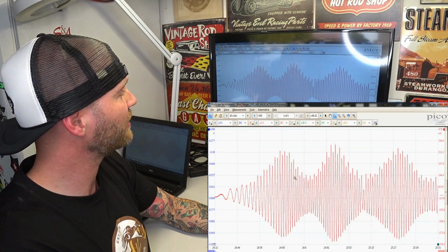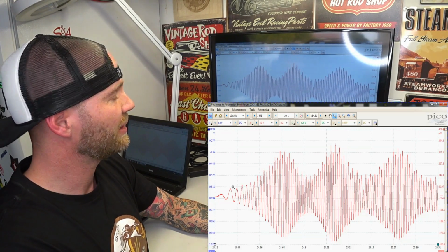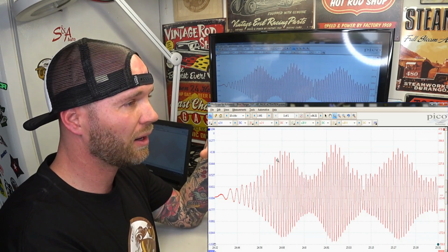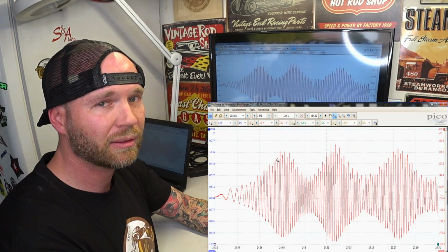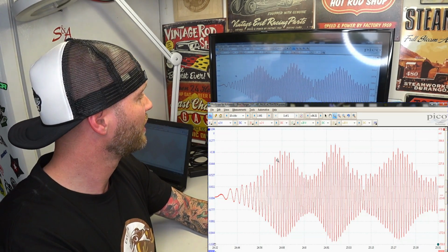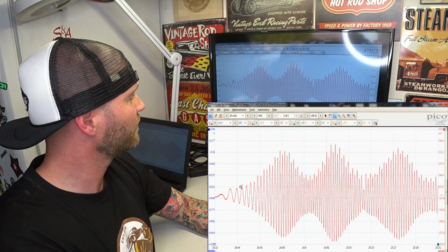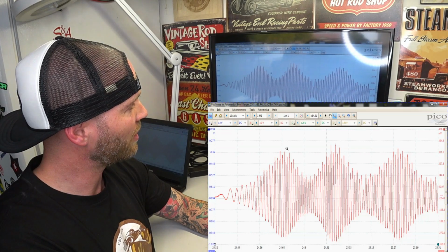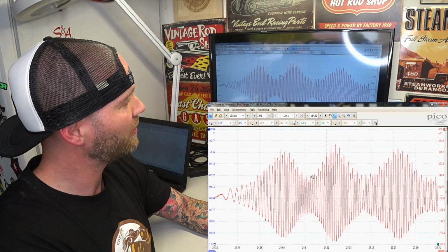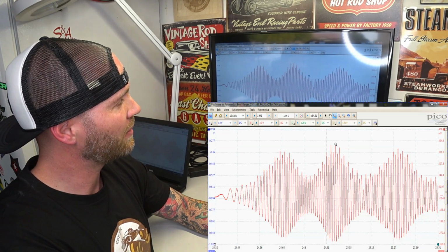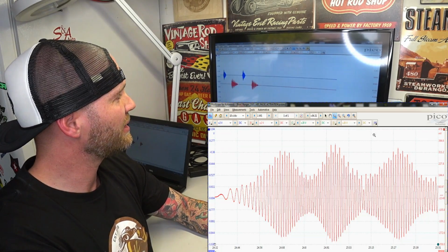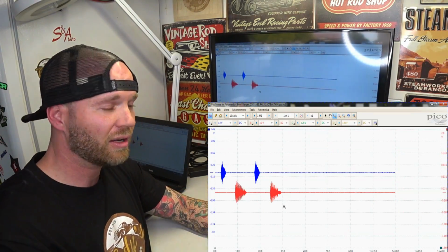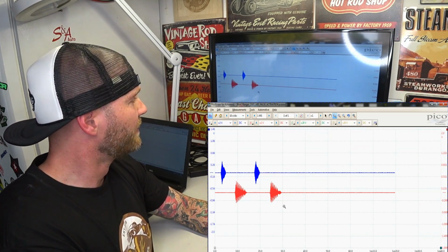That's exactly what we are seeing here: the tone wheel is not perfectly centered on that brake rotor. Here's where it's good, then the distance gets farther away so it drops down, then the distance comes back around so it goes up and drops down. Mind you, this wasn't anything I was seeing whatsoever on scan data.